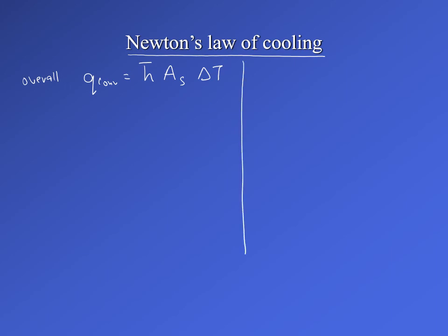And I will use this space on the right hand side. So what is Q convection? Q convection is the amount of heat that is transferred from the pipe surface to the fluid material flowing in the pipe. So Q convection ultimately results in the increase of the temperature of the fluid. So this we can write as m dot times Cp times the T mean outlet minus T mean inlet. So that is ultimately what our Q convection is.